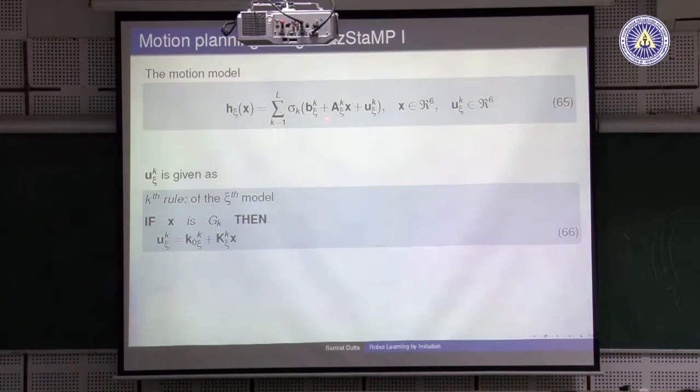It is nonlinear in the sense that these values will change because of the firing, how the system will be fired based on the nonlinear function, maybe the Gaussian function we are using here. Based on that, the system dynamics will change at each instant in the state space, and our job is to find out the values of these b k's, a k's, k i's and k zeros. That is our algorithm, basically finding out these parameters and the parameters inside it.